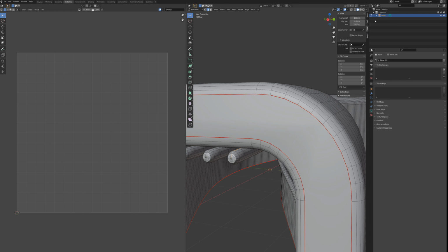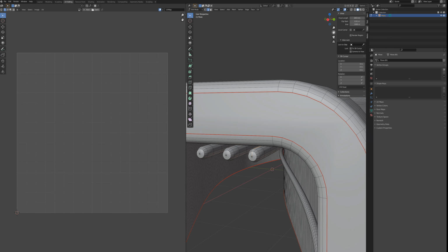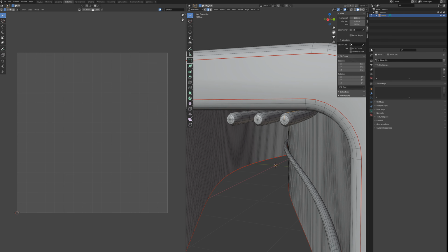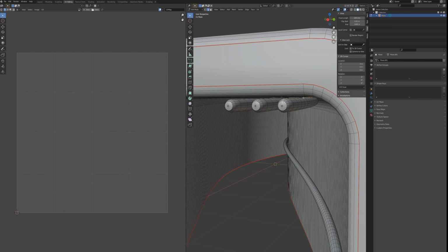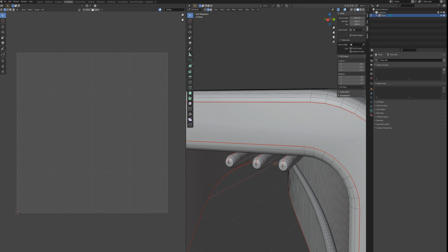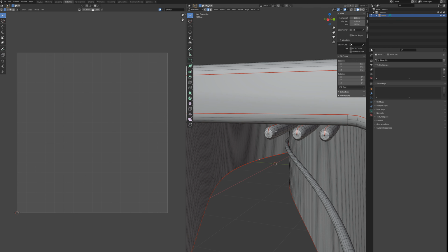Okay, I've selected an edge loop here, and it runs between the pipe and the roof all the way down to the other side, to the other end cap. I'm going to do the same thing on this one and the same thing on this one. Right click, mark them as seams, and I'll clear my selection and mark all of these edge rings as well.